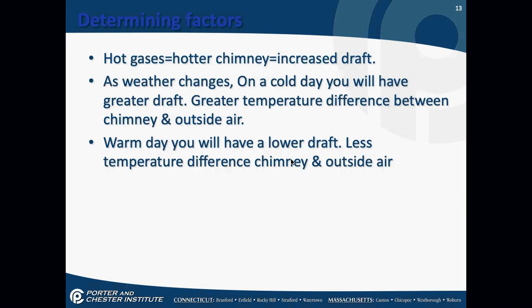As the weather changes, your draft will change. On a cold day, when I put hot gas into that chimney, I'm going to have a really awesome draft. There's a greater temperature difference between the chimney and the outside air. On a warm day, we have lower draft. Less temperature difference between the chimney and the outside air.